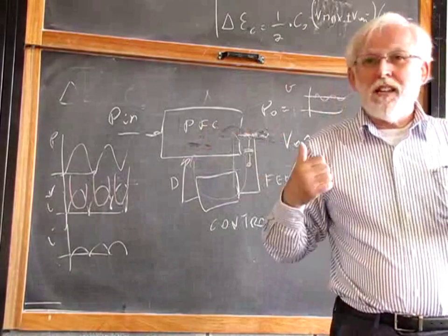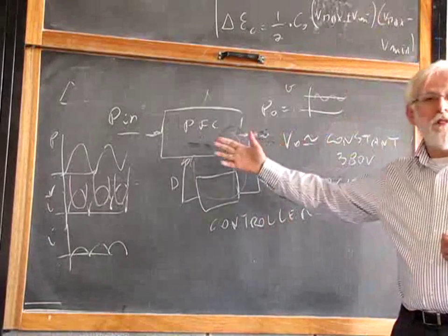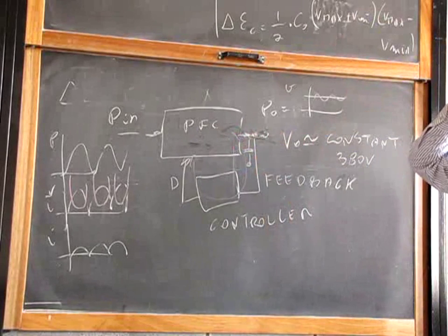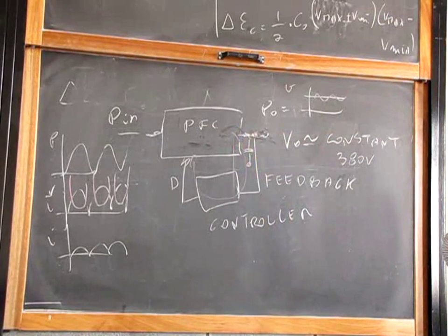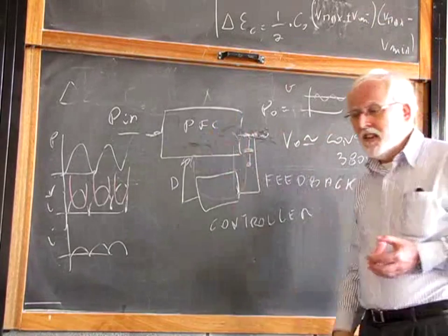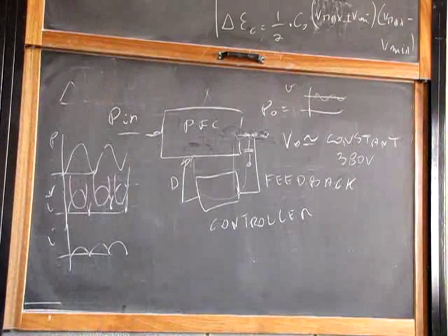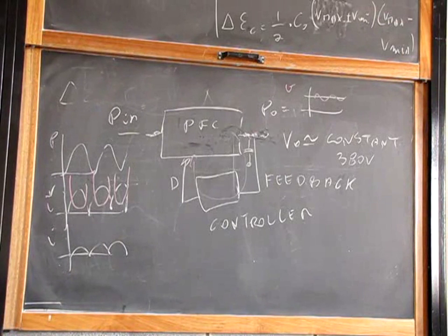And so, who cares about the uncontrollability of this boost converter? This boost converter is very nice, very well used in PFC circuit, because the bandwidth that I need is far smaller than the frequency of the right half plane zero. Okay, that's all. I cannot go into the detail on how this controller is made because we don't know yet how our controller is made in general.